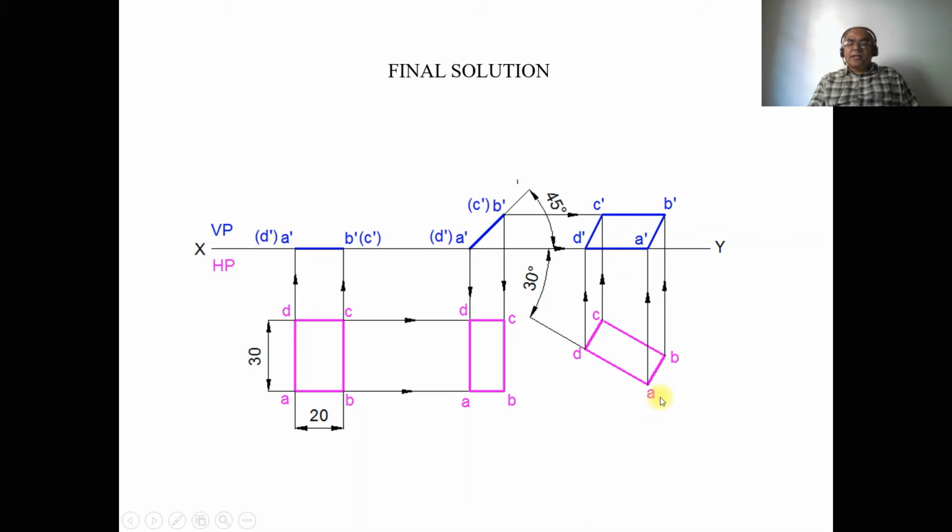Then, using the protractor with D as center, measure an angle of 90 degrees with respect to this 30 degree line and draw a perpendicular line. Similarly, with A as center, again with respect to the 30 degree line, measure an angle of 90 degrees and draw a perpendicular line. Then, using the compass with A as center, take the radius of A to B and also D to C, both of which have equal distances.